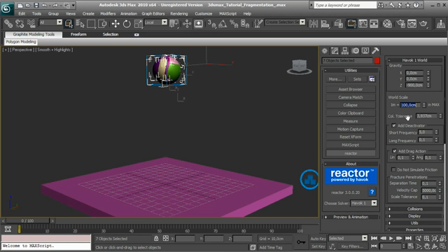And we have to change the collision tolerance to be more precise, because using something around 4 centimeters, we are saying that when a mesh is at 4 centimeters from another mesh, there will be a collision, and it is not so precise.